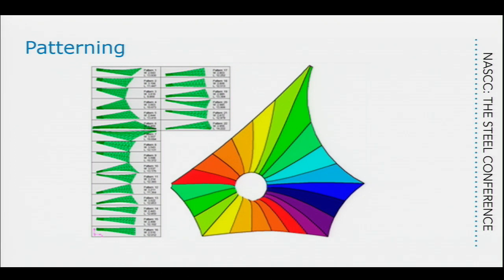So you can imagine that if I assume an isotropic material and then I establish a cutting pattern that pulls it in a different direction, it doesn't behave the way I want it to, and you get a lot of wrinkles. You might even get failure. So what happens is, once we establish a pattern, we have to actually run another analysis and decompose the stresses and make sure that once we get them in the orthogonal directions, that we still have a strong enough fabric.